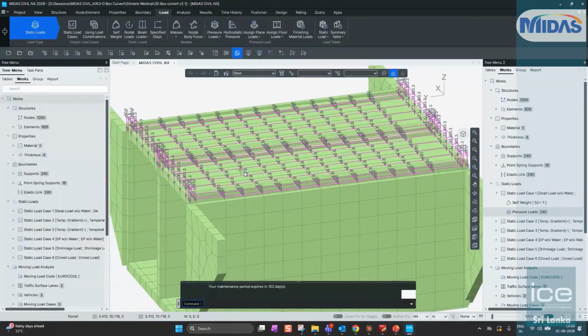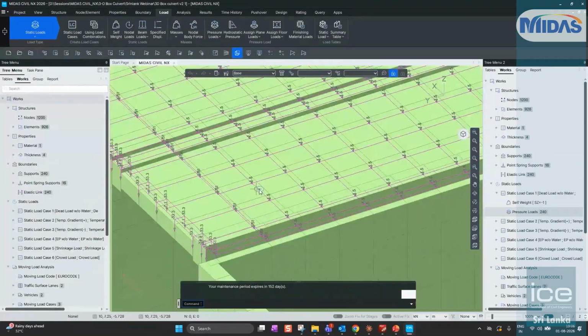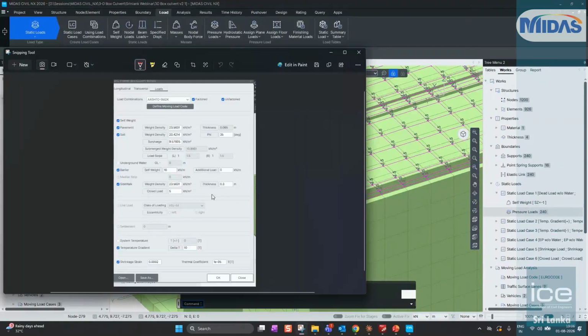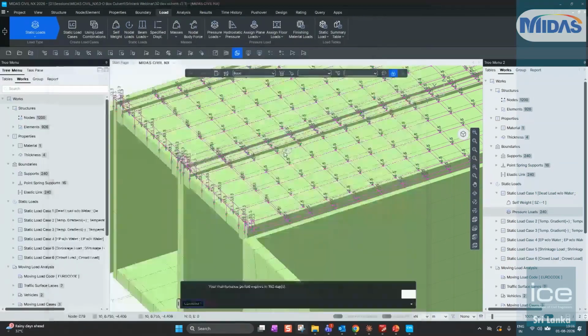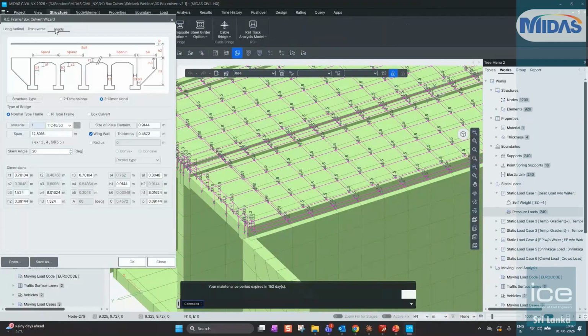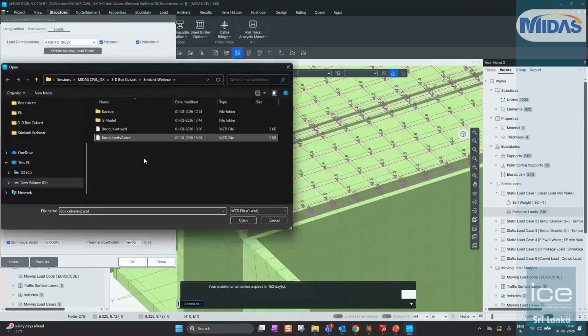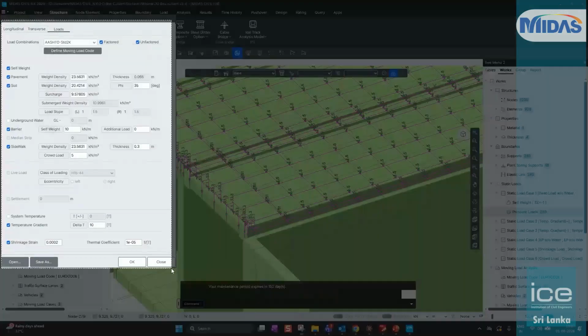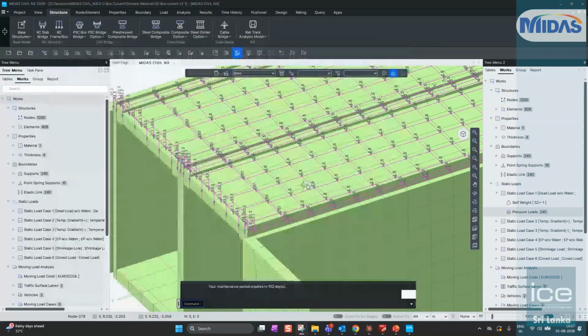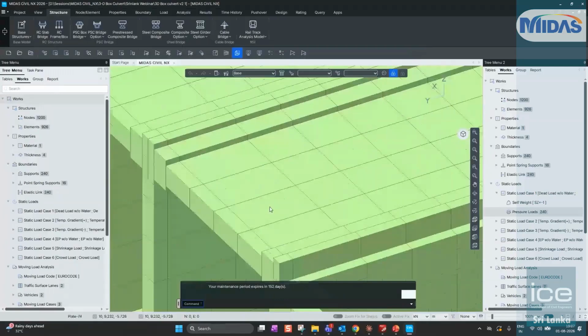So here you can see the pressure. The pressure is of 1.5 value. This is because of the pavement. If you directly go to check the values, we used a pavement density of 23.5631 times 0.065. That should give you 1.53 kilonewtons per meter square of UDL. Okay, I did this, I should not have removed that part. So I'll go to structures, loadings. So we checked, the pavement thickness basically gives you 1.51 kilonewtons per meter square of UDL.